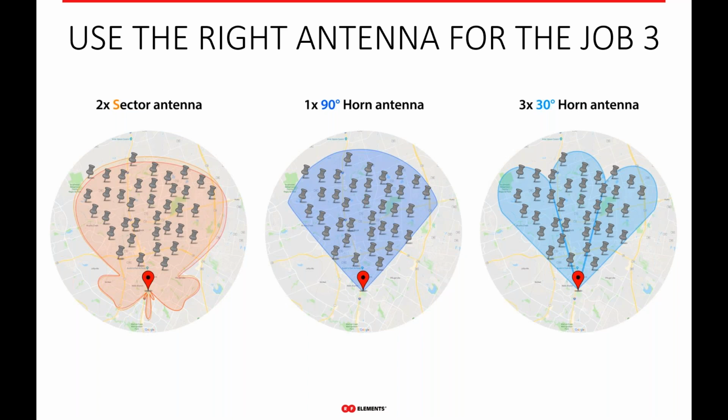You should use the right beam angle and the right gain that gives you precision over your coverage area. Or again, if you need that AP density in your tower, split that azimuth up into multiple different beam angles in order to cover that network.